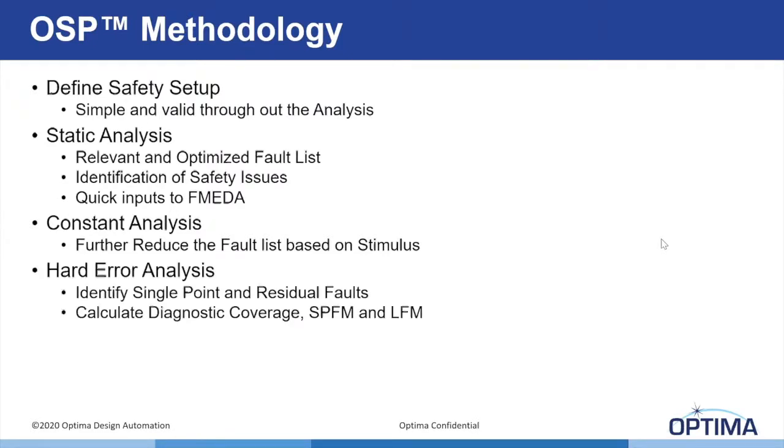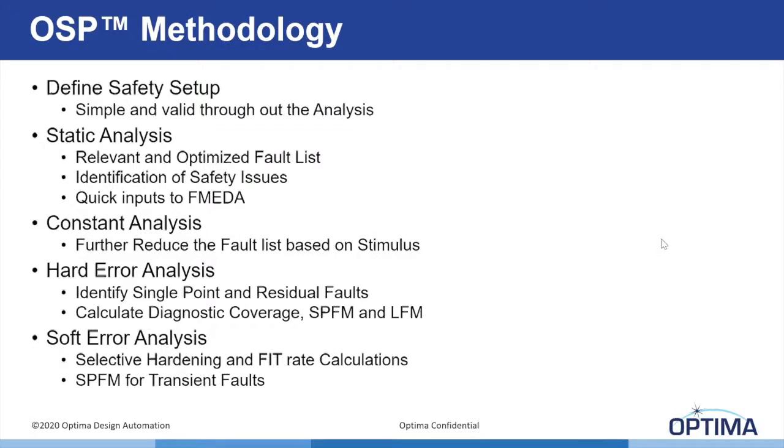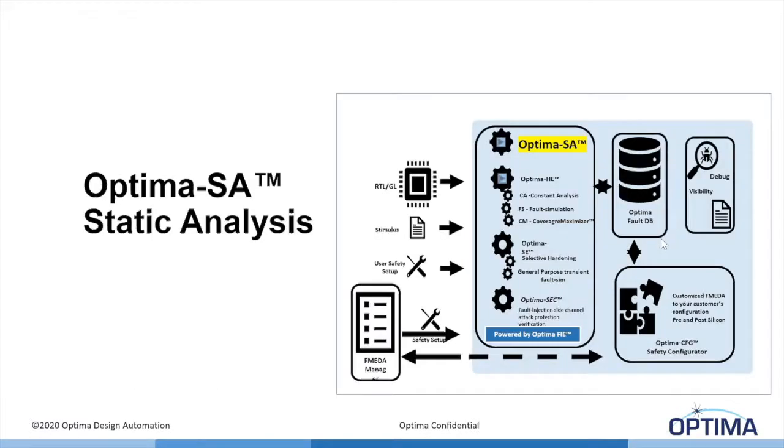Hard error analysis to identify single point and residual faults and calculate the diagnostic coverages SPFM and LFM. Soft error analysis is done for the selective hardening and the FIT rate calculations, as well as SPFM for transient faults. Let's look in detail at the Optima SA static analysis.